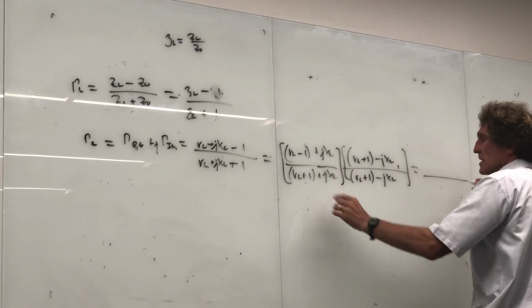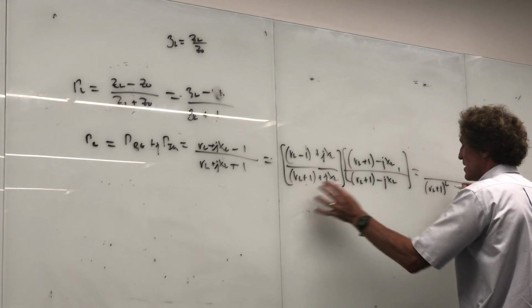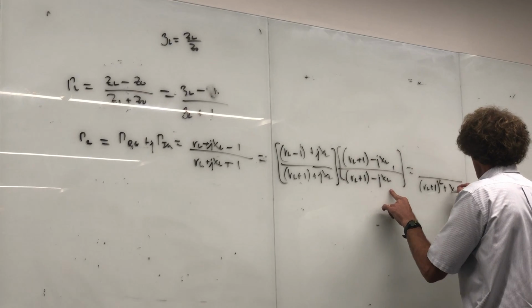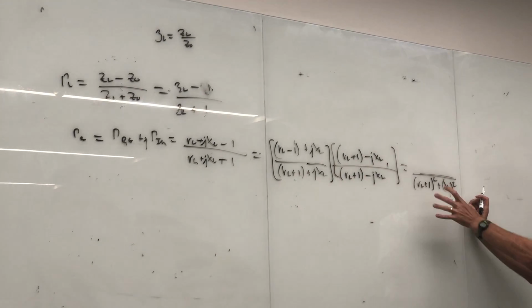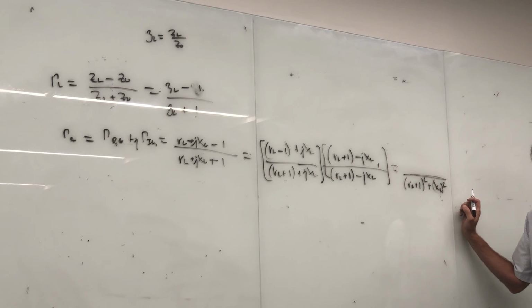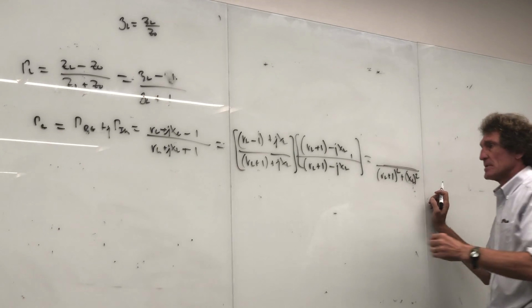And the reason I'm doing it is now downstairs I simply get the real part, R_L plus 1 squared, and I get the imaginary part, plus X_L magnitude squared. So this times this renders only this. There's no imaginary part. Do you all see that, class? With me? Now what happens upstairs?